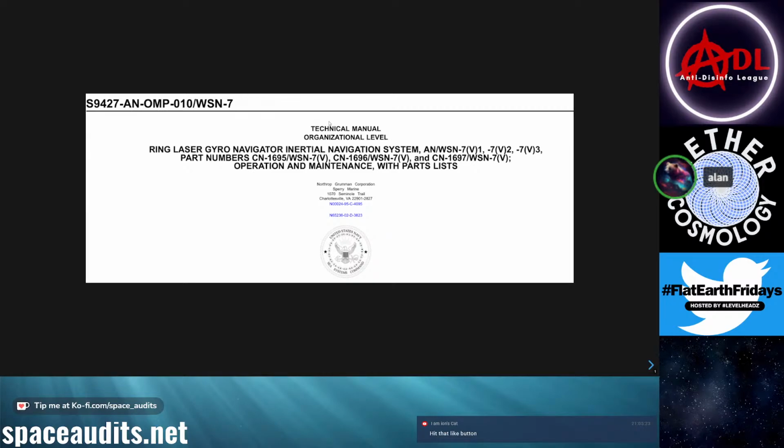Basically, it's just averaging out the readings and how the device is functioning in reference to where it's at. The whole time it's calibrating, it has to be stationary, and then it gets multiple inputs for reference. That's how you get it calibrated, so you can get it to the point where you can quote unquote turn it on and it just knows where it's at. Like I said, the Kalman filter takes care of all that. It backs all that information up and keeps it logged for reference. So when they do a correction to the system like that, it's already backed up through the Kalman filter. So shout out to Kalman.